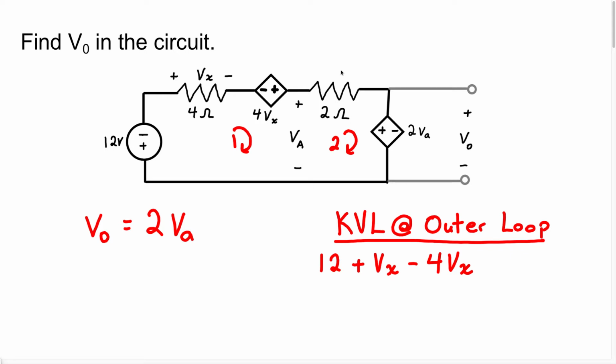So now when we get to this particular element, there is no voltage label across this resistor. So what should we do? Should we just skip over it? No. What we're going to do is label a voltage for this particular resistor. So for me, I'm going to write this as plus, minus, and I'm going to call it V1. So even though they did not label a voltage across this resistor, we know as we walk around this resistor, it is going to have a voltage drop. So I'm just going to label it plus to minus. Now remember, you can choose the polarity. I just chose it as a voltage drop.